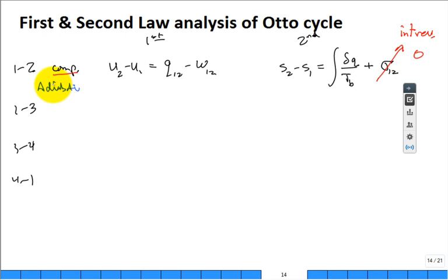If there's no time for heat transfer, then the student that is brand new in Thermo 2, more than half of them will say, you mean if I have a gas and there's no heat transfer, then I know what the temperature change is, 0. Because if it's adiabatic, no heat transfer, then the final temperature has to be equal to the initial temperature. But you passed Thermo 1. You're not going to make that mistake. Right? No way.